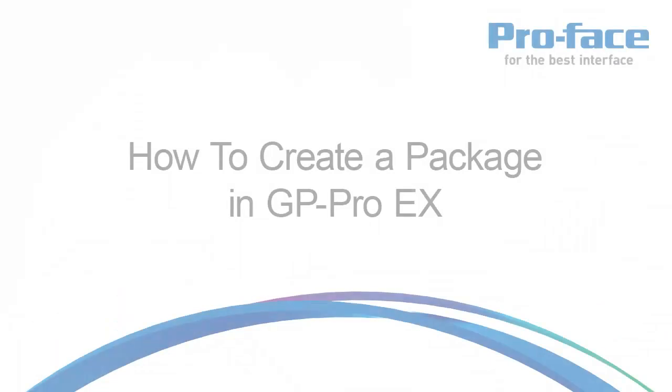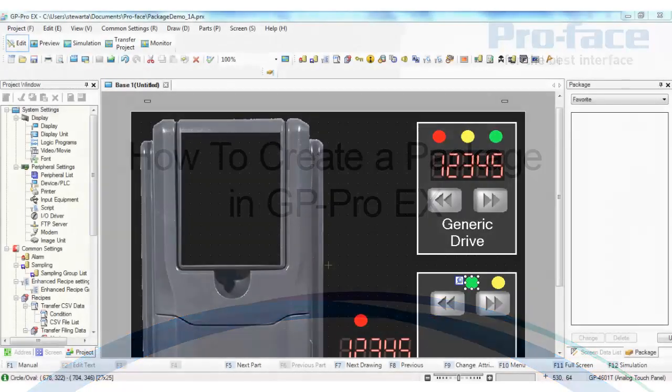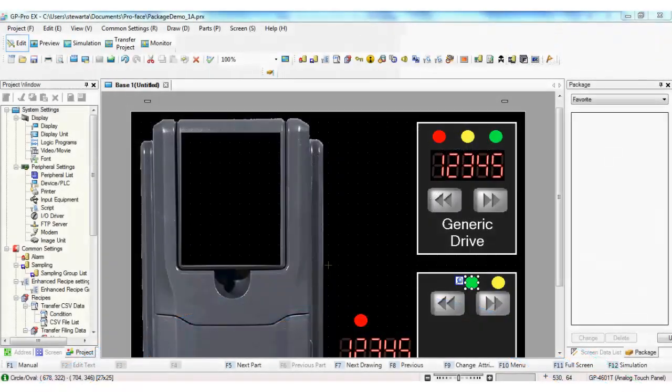In this training module, we will show you how to create a package using the package function in GP Pro EX. The package function allows you to build parts and store them within GP Pro EX for repetitive use, eliminating the need to rebuild the part each time. In this example, we're going to build an AC drive.